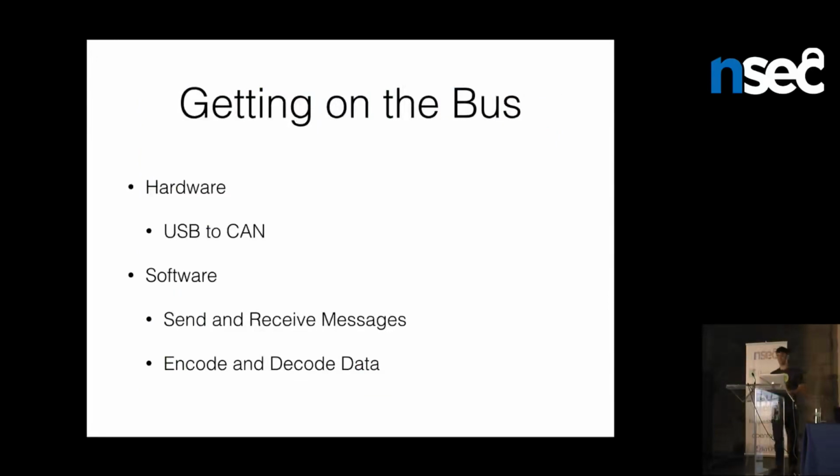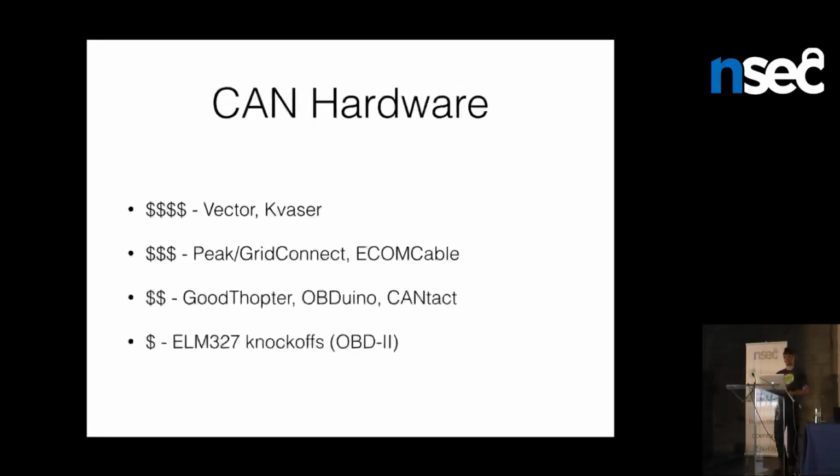this system? You'll need some hardware and software. Hardware because MacBook Pros don't have a CAN bus port on them, so you'll need something to go to CAN. In this case, most of them are USB to CAN, some are Ethernet to CAN, or even some ancient RS-232 to CAN, which, don't do that, because RS-232 can't even do the full bit rate that CAN needs to work, so those are terrible. And then you'll need some software, obviously, to do the send and receive and to encode and decode data in a way that makes sense. You stick these things together and you get some toolkits that let you talk to cars.